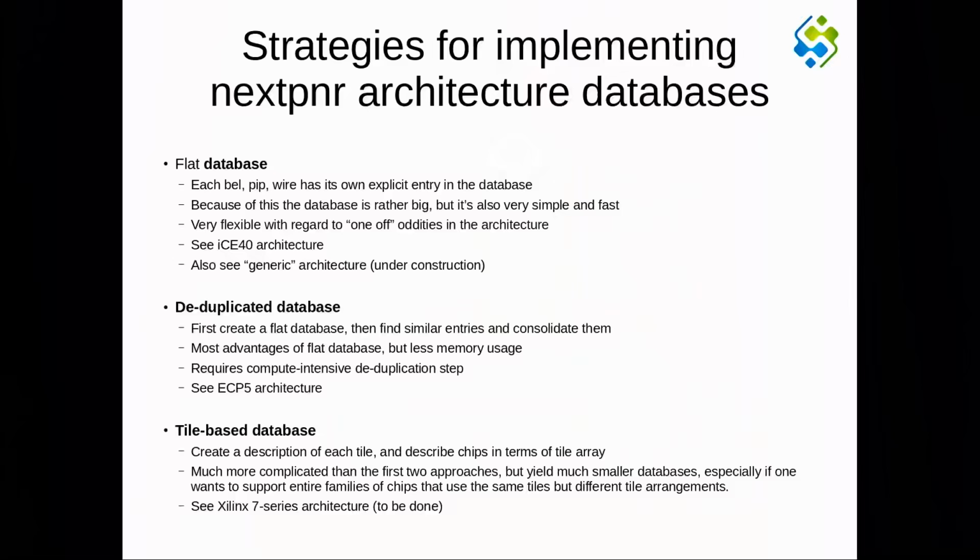The nice thing about the deduplicated database is that you can still start with a flat database. So if your chip has a couple of irregularities, you don't need to do anything special. Whenever there is an irregular structure on your chip, it will just fail to deduplicate it and everything will be fine. But the downside is your chip must be at least small enough so that it's feasible to generate a flat database in the first place, and then we can deduplicate it. And for really large chips, that's not really an option.